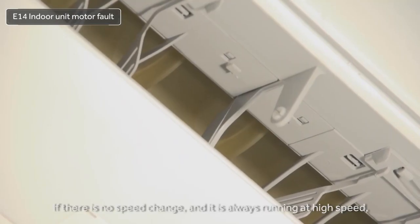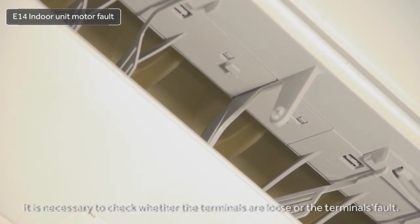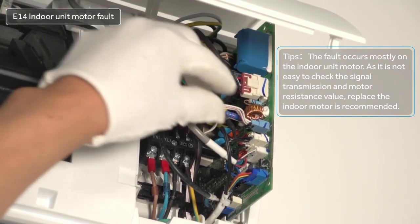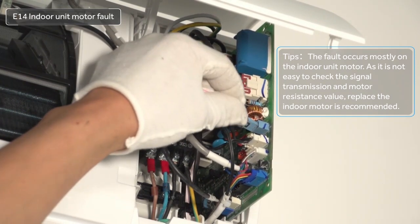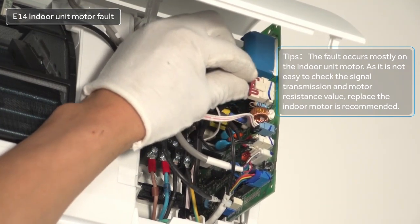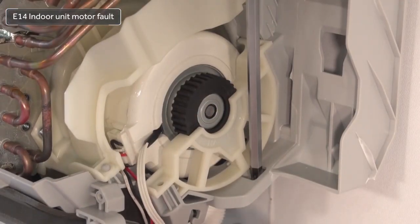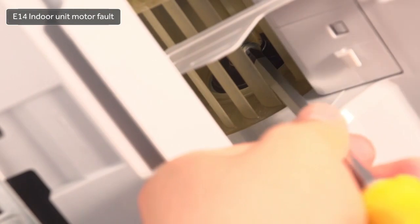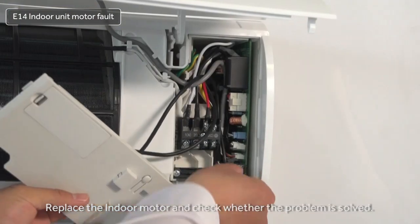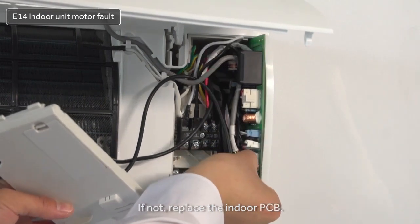If there is no speed change and it is always running at high speed, it is necessary to check whether the terminals are loose or faulty. Fasten the terminals and check whether the problem is solved. If not, replace the indoor motor. Replace the indoor motor and check whether the problem is solved. If not, replace the indoor PCB.